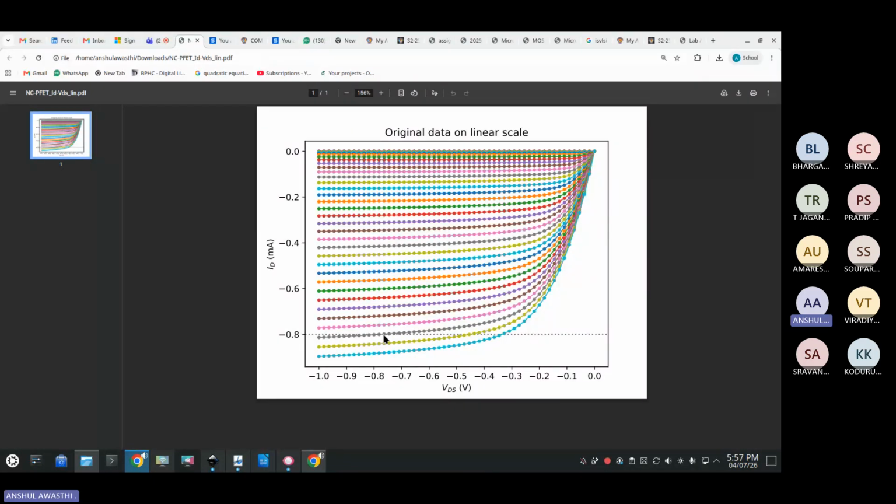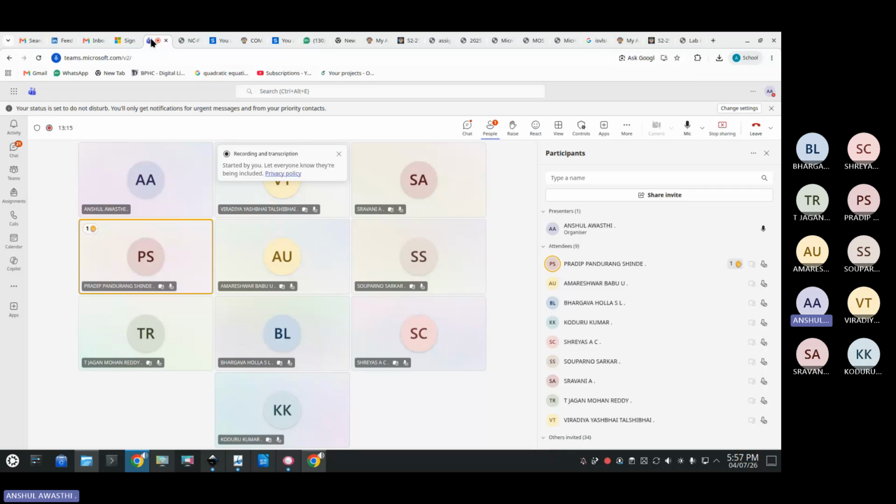If I want this type of graph, that means ID/VDS relations for 1000 values or 100 values of VGS, the technique we adopted in experiment number 3 is not feasible. We have to go for some other parameterization. This type of variation is particularly needed for research purposes or observations, so we have to make an advancement in the tool.